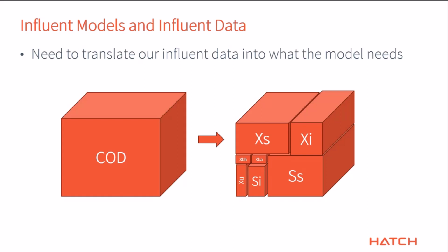The soluble substrate, this is the SS down here, the soluble substrate and the soluble inert, they of course float through, they're not going to settle out, but the particulate stuff will. And of course, the biodegradable things, XS and SS, will undergo transformation in the bioreactor as they are acted upon by the biomass. And here's some biomass that's coming in.